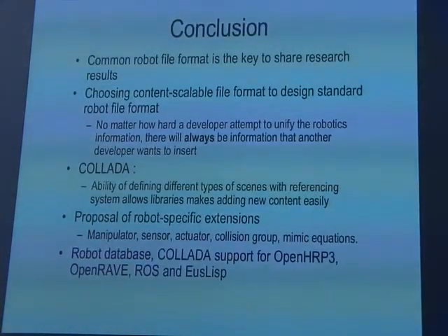So here is the conclusion. I think a common robot file format is the key to sharing between different types of robot platforms. And we chose a content-scalable file format, the COLLADA format, because no matter how hard developers attempt to unify the robotics information, there will always be information that another developer wants to insert.